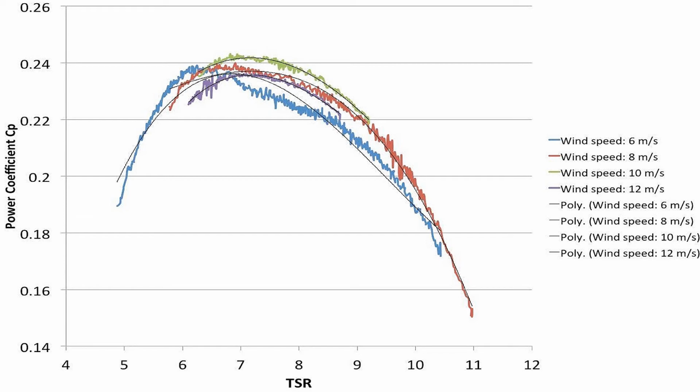The TSR of our wind turbine at this point was measured to be 7.2, which is considerably higher than our target TSR of 4.8. This has led us to believe that the initial design TSR, which we quoted early in the design process, was inaccurate and does not correspond to the wind turbine we actually designed. We think that the design of our blades caused the TSR to be too high, causing tip-end losses and losses due to the blades flowing through turbulent air.